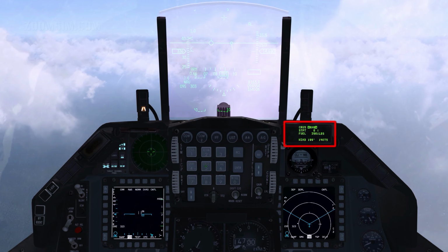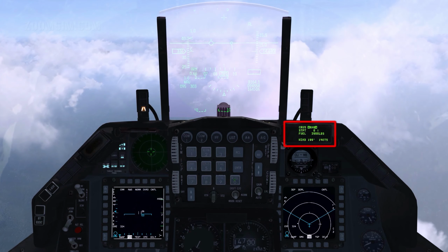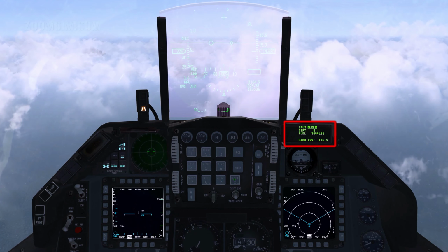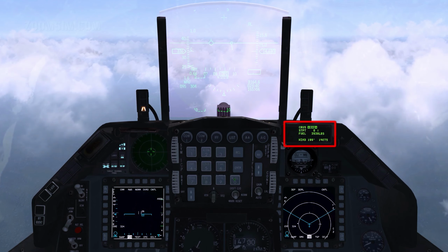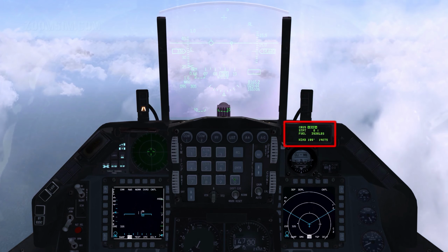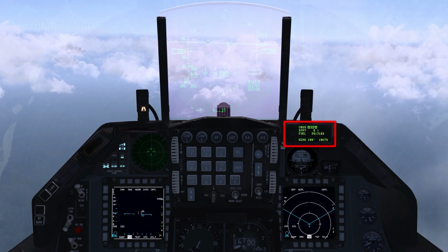When range is mode selected, best conserve fuel speed at the current altitude is indicated by a caret on the HUD speed tape. The active Steerpoint can be changed with the previous next rocker switch. Wind direction and speed are displayed.